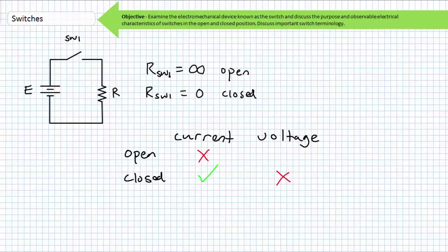Depending on its position in the circuit, a point I'll come back to clarify, an open switch will have voltage drop across it. For the case of a single switch in series with an electrical load, all voltage will be dropped across the switch when the switch is open.